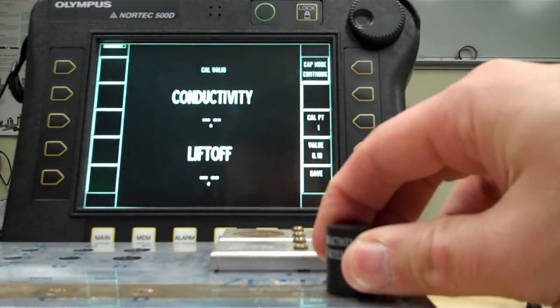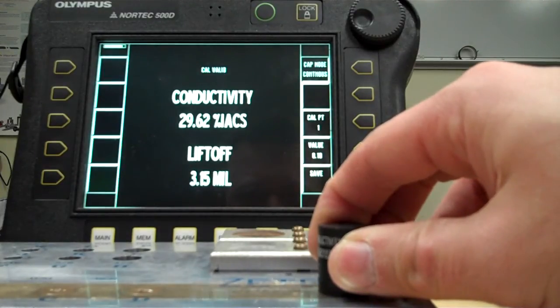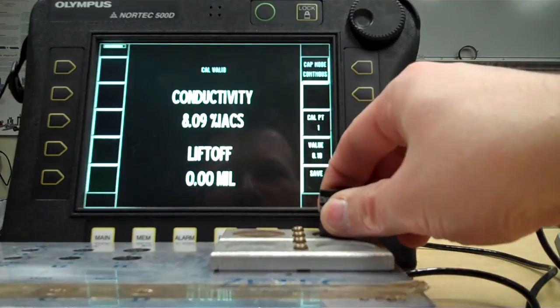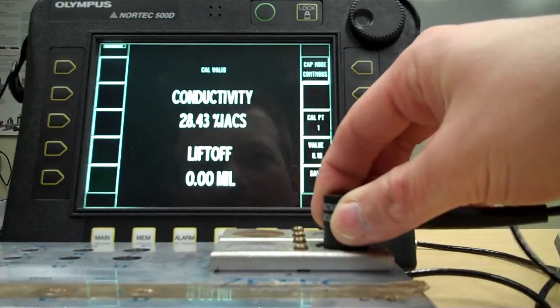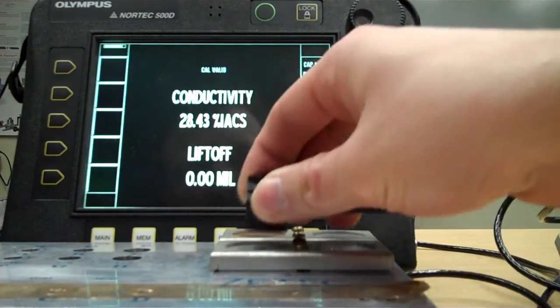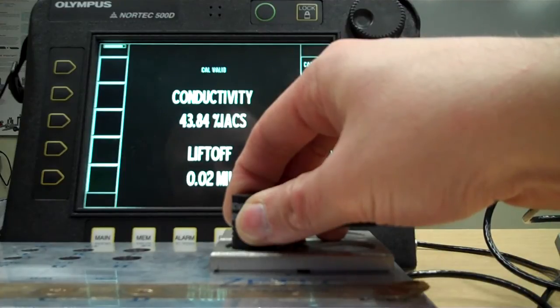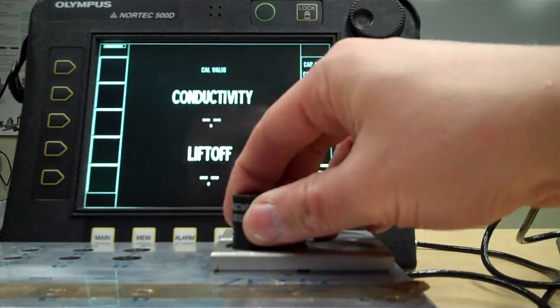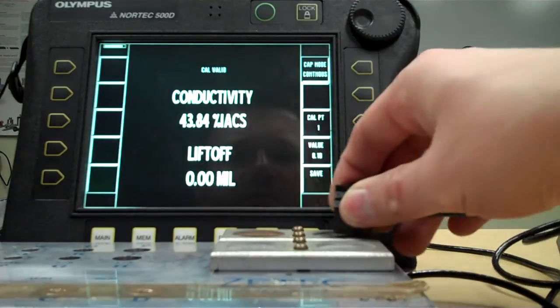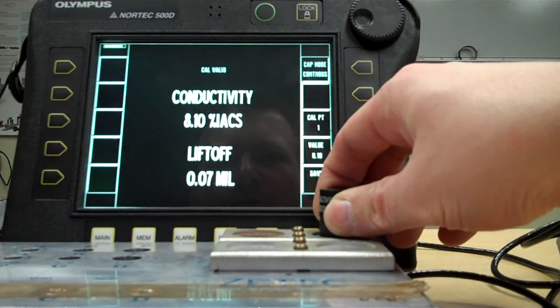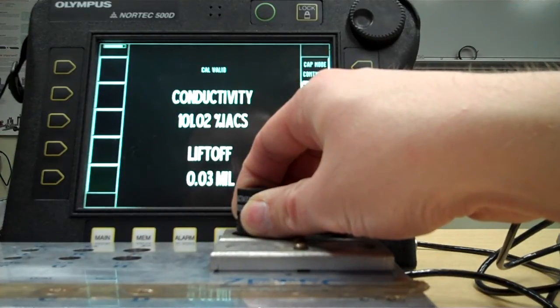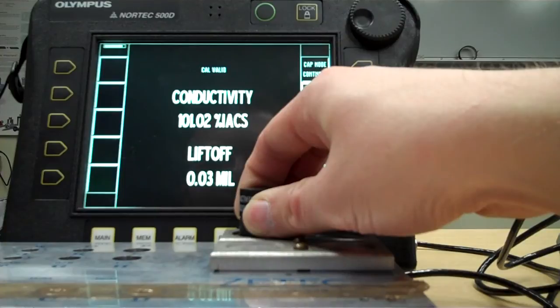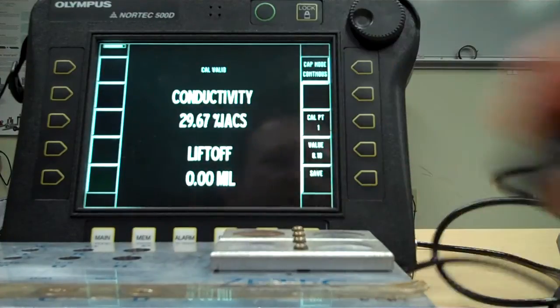So, just taking a look back at these same things. So that's 8, that's lead. Let's go in the middle. This says 29.3. Okay, we're about 1% off. That's not horrible. Okay, about the same. This says about 45. We're about 1.5% off there. We calibrated to the lead, 8.1. We calibrated to the copper. There we are, 100.1. Okay, and it's a continuous thing, so it's always measuring as well.